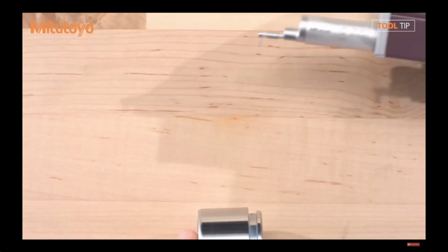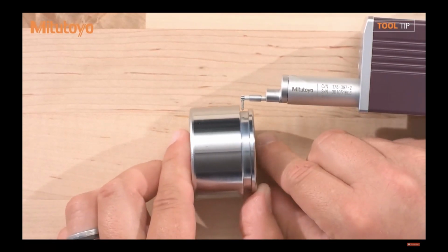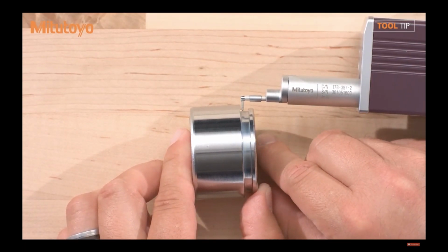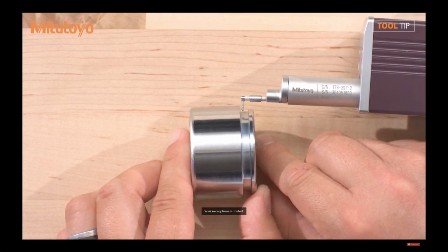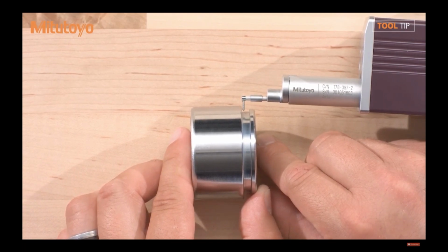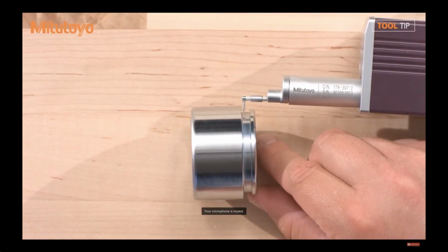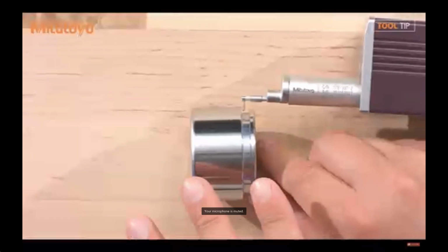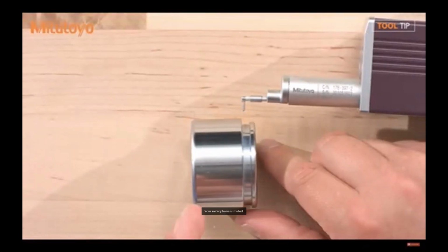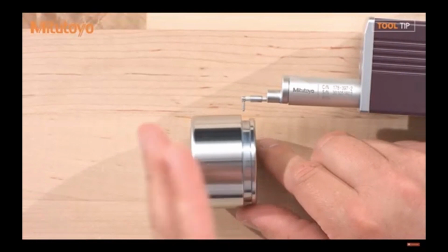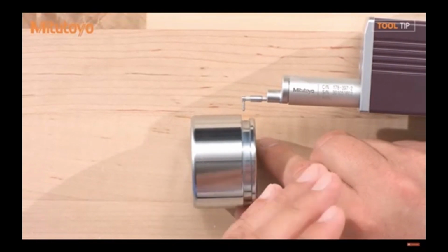However, if I bring my skidless system in, now you'll notice I can easily not only reach the groove that needs to be measured, but I still have room to measure from side to side along that groove. So let's say that I have a part with a groove that's a little deeper. It's a little more narrow. Is there some flexibility in the type of styli that I can use? Absolutely. With both the skidded and the skidless systems, there are different styli that can be used with that system. So if you need to reach deeper within a part or down within a groove, maybe at a little bit of an angle for a geared tooth, we can accommodate for that. There are more styli options available for skidless systems than there are for skidded systems typically, though.